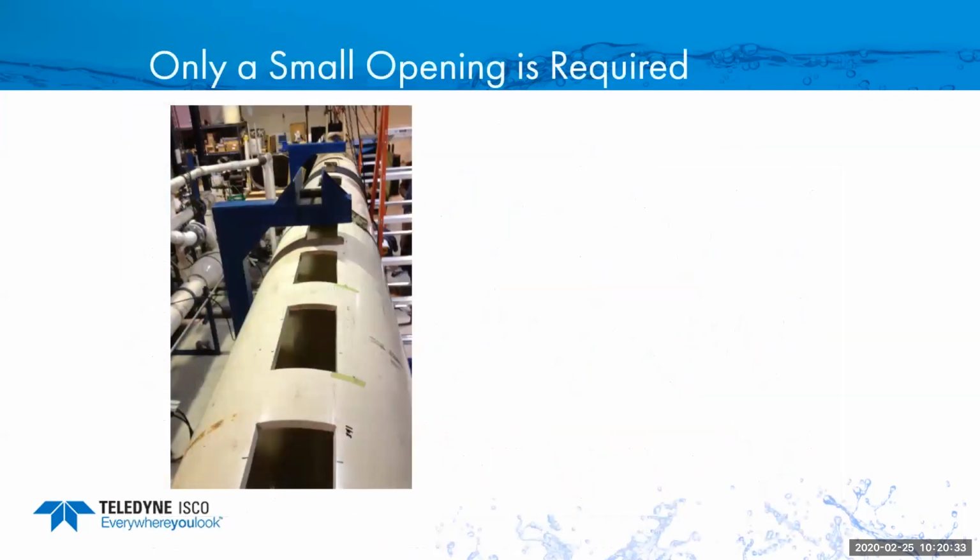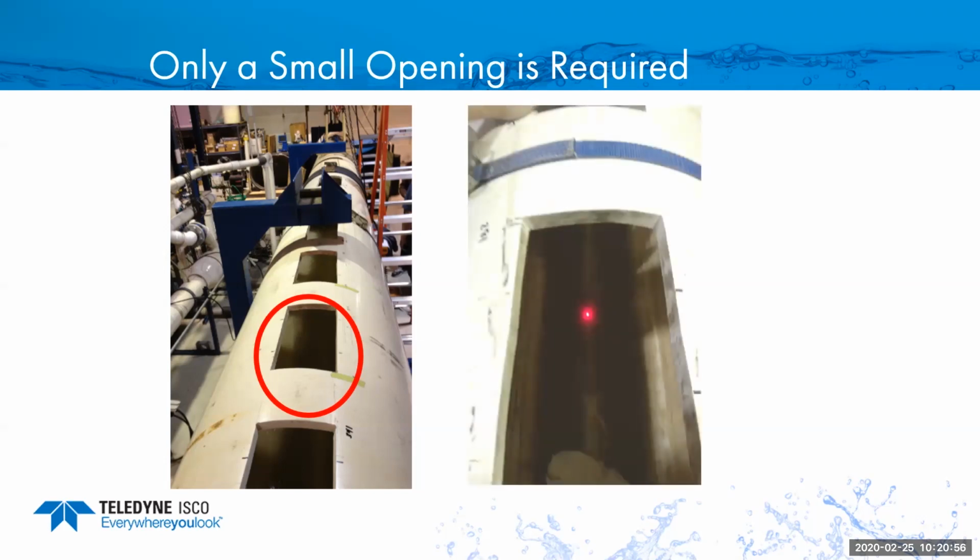Okay, so I included some of these pictures to give you some application ideas of what you can do to install one of these. Really all we need is a small opening in the top of a pipe. This happens to be the ISCO Flow Lab. You'll see we have a bunch of these notched out. So depending on how high up the laser is in our testing, we hit the right opening. But really you only need an area that's about 4 inches by maybe 10 to 12 inches long. This is a good shot of the laser actually hitting the water itself.